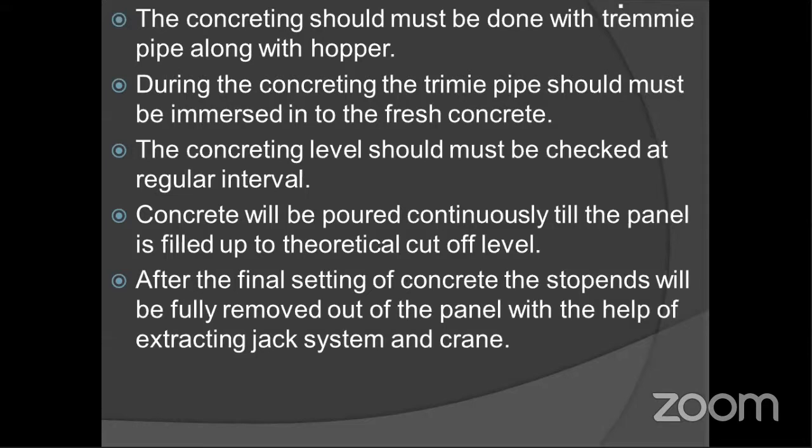And also we should try to put the panel numbers with date, so that if anything happens in future with this information, we can get the casting date and everything. That will be very beneficial for us.